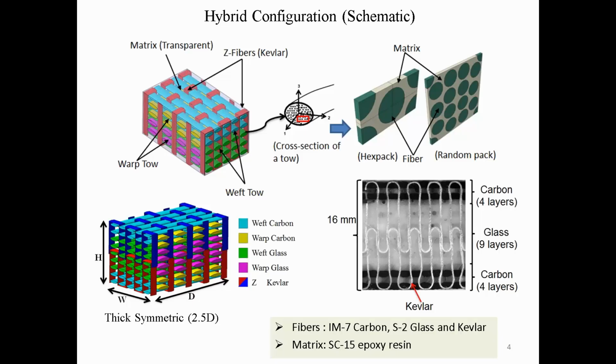So the good thing about this particular material, which is very widely used and very popular, is that most of the composite community faces the delamination problem in laminated composites, whereas with this textile composite, this 3D textile composite, because of the thickness direction reinforcement, the delamination is prevented.